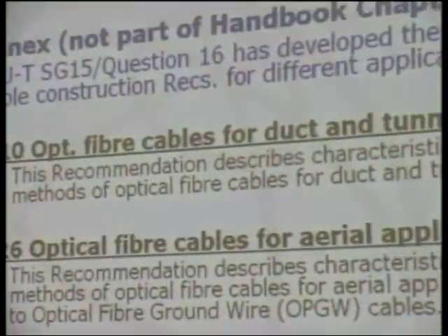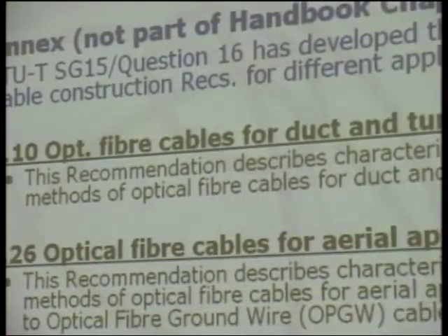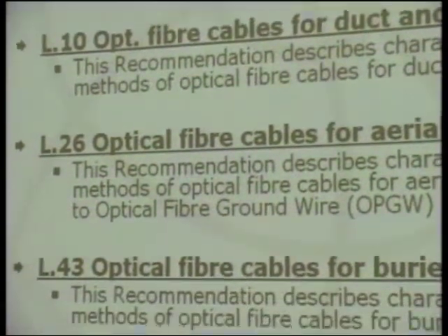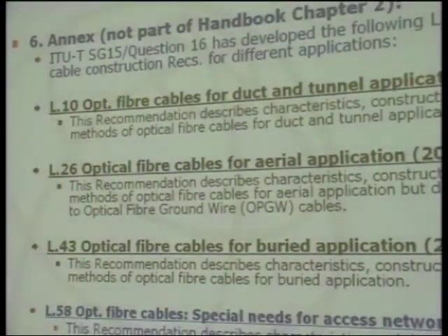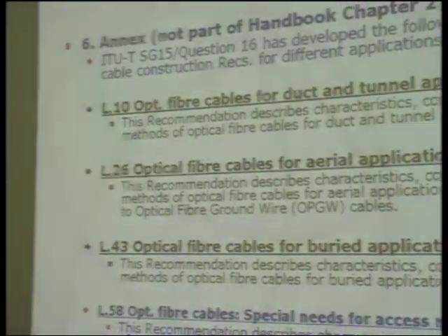Buried cables are laid down directly in the ground, so in the soil. While in duct applications, you have a kind of duct, which can be a stone grid or a cement grid in which you can lay down your cable. You can say a kind of pipes. It can be cement, concrete installations in which you can lay down your cable later. So there's a distinction between duct cables and directly buried cables.